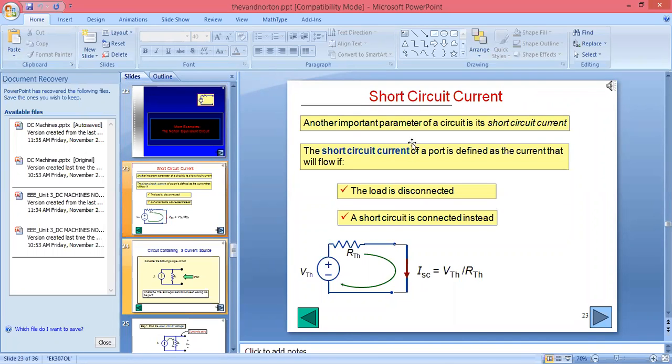If we have the Thevenin circuit, at that time we can calculate the shunt current. How? Because we make the load, that is, we disconnect it. So you will get the value for Ish, which according to Ohm's law is V upon R, VTH upon RTH. So by using source transformation you will get the value, or we can solve by a simple method. By using any method, you can solve for the value of Ish. But here you are supposed to find the Thevenin equivalent resistance, similarly to how we find it in the Thevenin circuit.